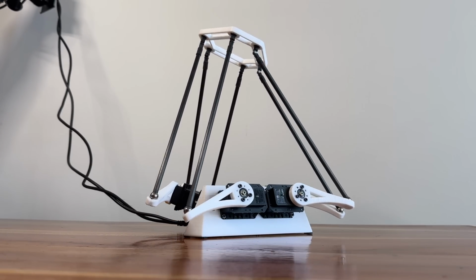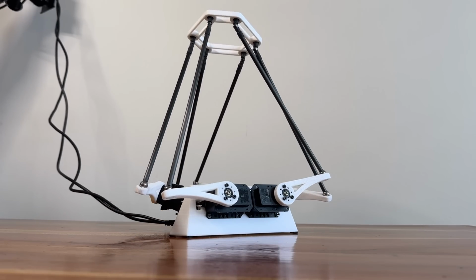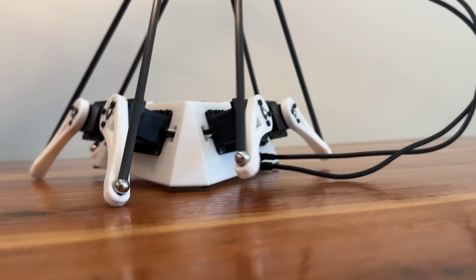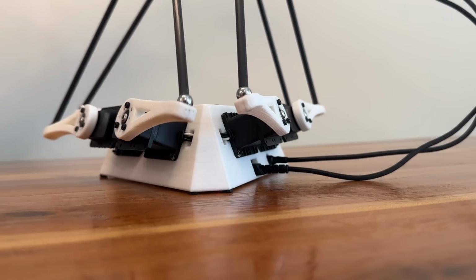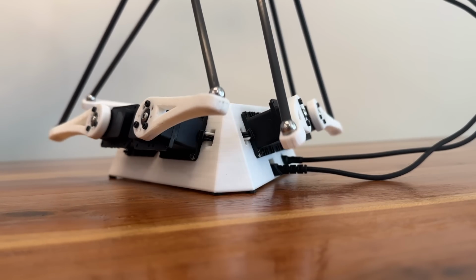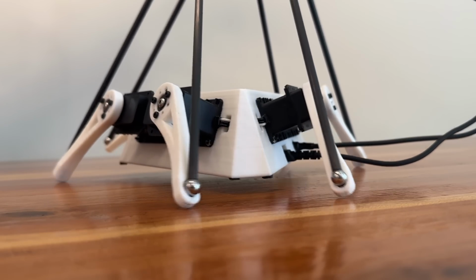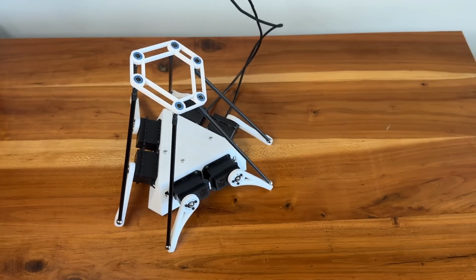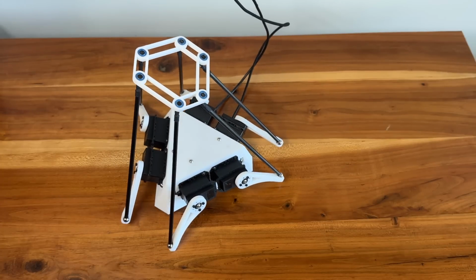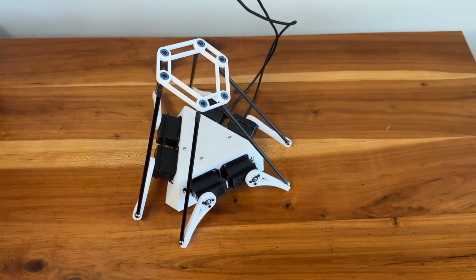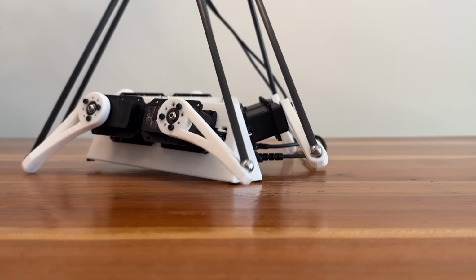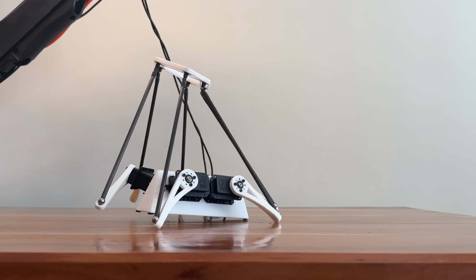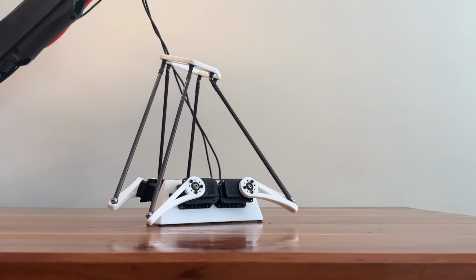I think this was the most interesting solution the algorithm was able to find. It's a movement where 5 of the arms hit the ground, making the bot take one slow, large step at a time. The fastest one is this, that uses 3 of its arms to walk. Even though the steps this one takes are smaller than the last, they are much more efficient, with parts of the base moving during most of each cycle.